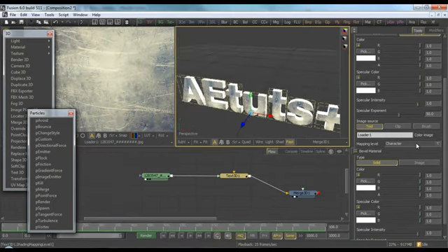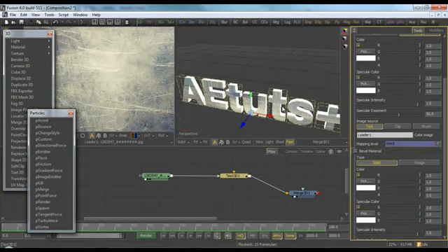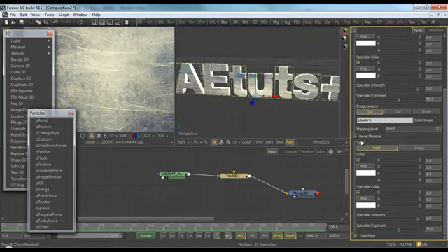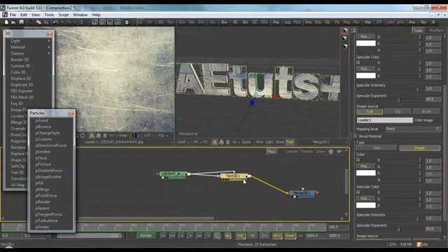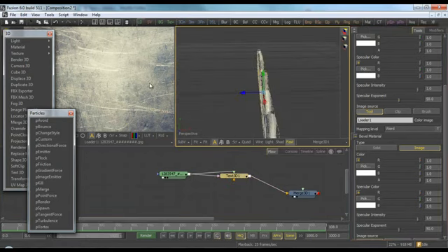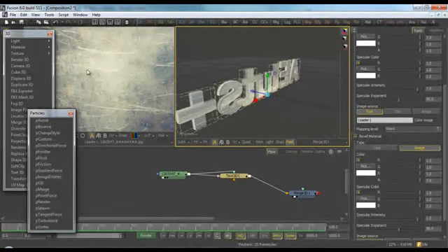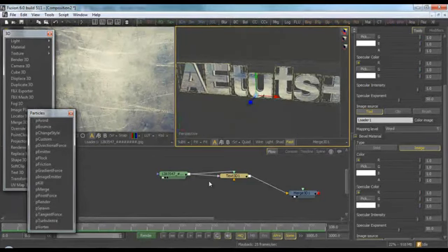And we'll set the mapping level to World. Yeah, World. Bevel material type image. So there another input shows up, and let's connect it to this input. And so we have a texture everywhere. We have it on the front face, on the back side, and on the bevels.